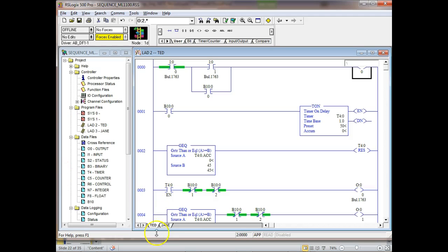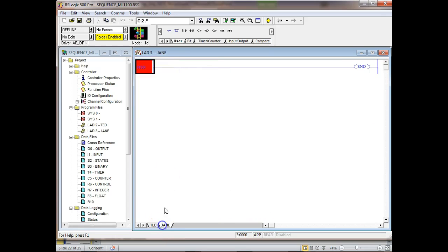But notice as soon as I set up that new program file, it automatically put an END in there. And this is an unconditional jump. This will always jump us back to run what? 0. Every time it's entered. I can't even put an input device inside that rung. Allen Bradley won't let us do that. Siemens doesn't give you the end. You just know it's what? You just know it's there. They don't put the end instruction out there.